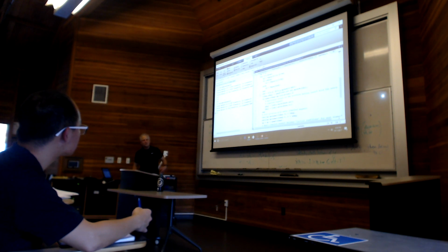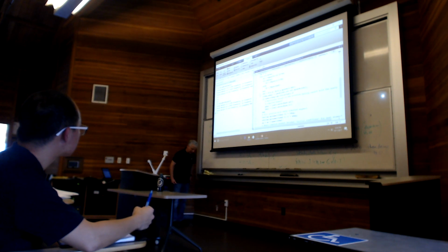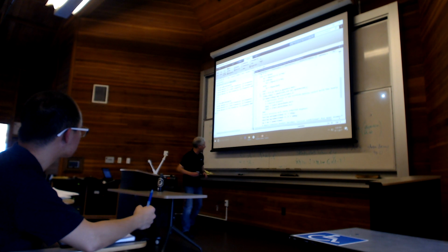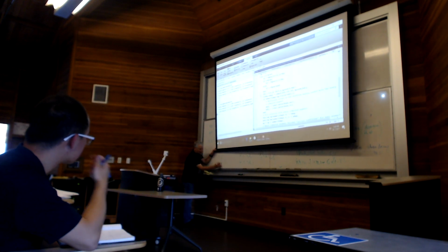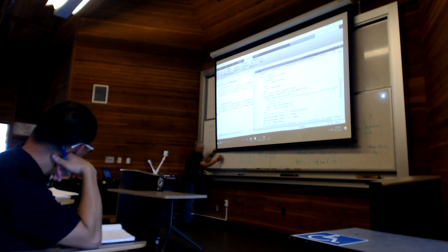In Simulink, you just go to, I forget what library it is, but there's a delay block in Simulink. I think it's called transport delay. It's called transport delay because of my example. Remember my example with the shower, right? The reason why there's a delay from doing something here to there is because literally material has to be transported.